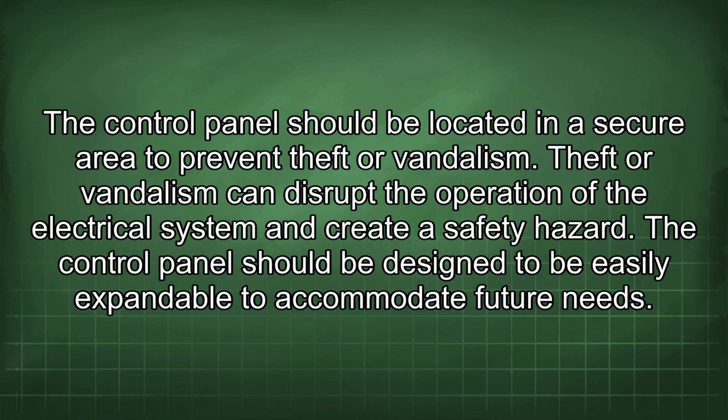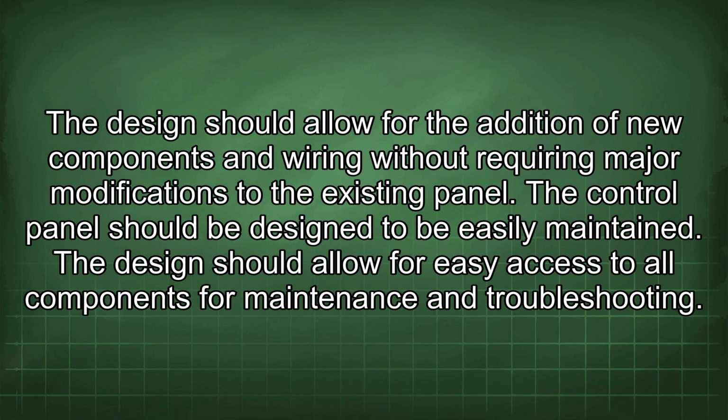The control panel should be designed to be easily expandable to accommodate future needs. The design should allow for the addition of new components and wiring without requiring major modifications to the existing panel. The control panel should be designed to be easily maintained. The design should allow for easy access to all components for maintenance and troubleshooting.